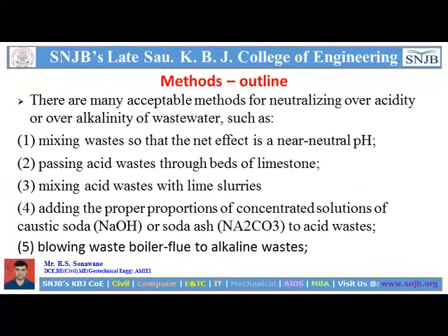So here are some methods related to neutralization, that is, a method outline. There are many acceptable methods of neutralizing over-acidity or over-alkalinity of wastewater, such as you can see here. There are many different types of neutralization methods for acidic and alkaline waste. The first method is mixing wastes so that the net effect is near a neutral pH. So sometimes by mixing wastes, pH is maintained, neutral pH is maintained.